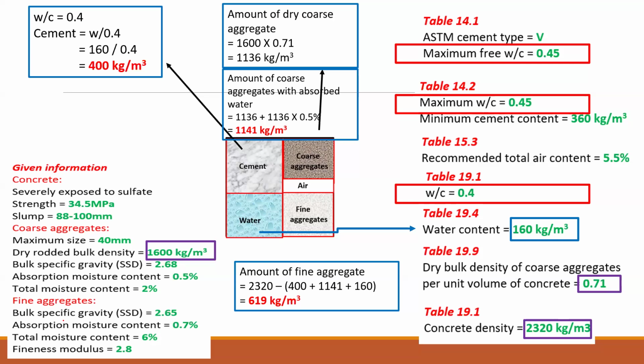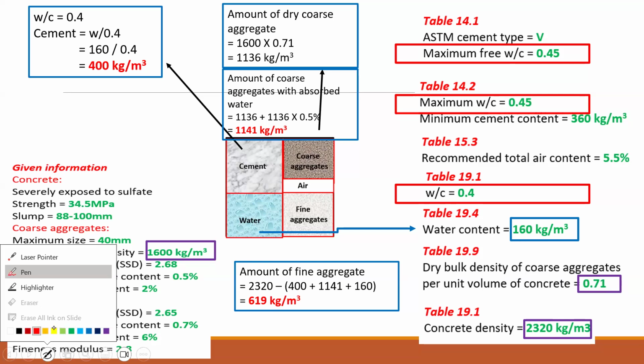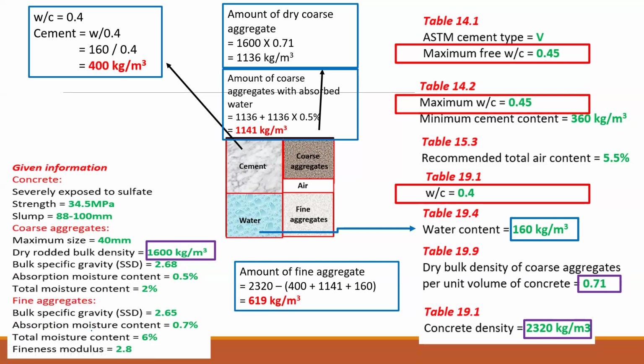So what's the issue? We haven't finished. We need to do a water correction. What is the water correction? That is this. So coarse aggregate is coming with 2% of water.